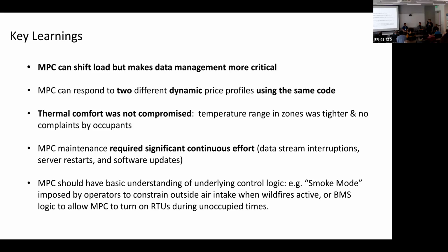However, running the MPC required a continuous effort in dealing with data stream interruptions, server restarts, software updates, and a whole sort of issues that are usually not talked about. And furthermore, because this is a supervisory controller, it relies on knowing what the underlying control logic is. In our case, during one of the tests, there were wildfires around here, and the facility operator completely shut off the outside air intake, which the MPC uses. And so the consumption of the MPC was actually much higher than what we expected. So we have to address that.